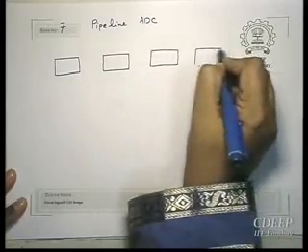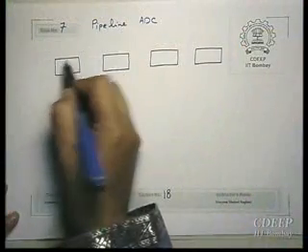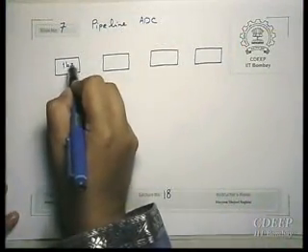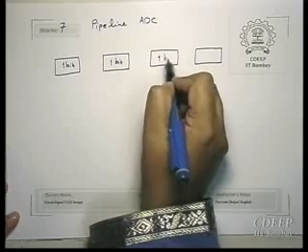into n cycles. So it's like a SAR ADC. You were doing a 1 bit conversion every cycle, and it was a sequential conversion. Here it also says, okay, you do it in sequence, don't do it in parallel like flash. However, you can choose to have more than 1 bit per stage, or if you want you can make it 1 bit per stage. Let's suppose we have 1 bit per stage. What does it mean? Okay, so we have the same stages.